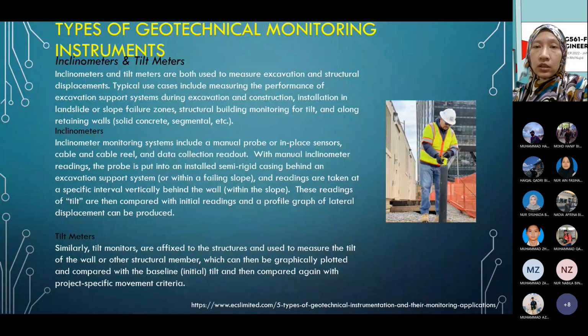Using the initial data input or parameters at the early stage of construction, you can make predictions. So the predictions come from a data set collected through the inclinometers, and then by using a proper theoretical equation, you can calculate the future settlement.